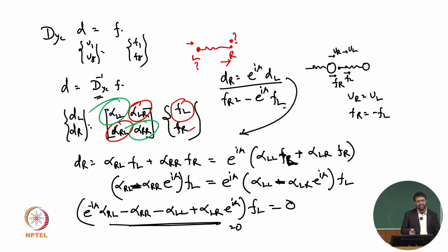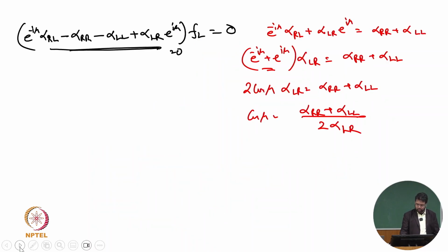You will see those two also will remain the same. Means these two will be equal and these two will be equal. So this one will eventually become equal once the matrices are symmetric. So this happens only when your mass matrix and stiffness matrix are symmetric. And if you see, in most cases our mass matrix and stiffness matrix all become symmetric. They are not asymmetric.